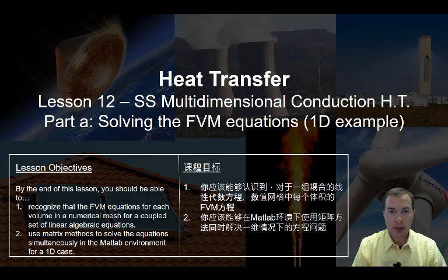By the end of this lesson, you should be able to recognize that the finite volume method equations for each volume in a numerical mesh form a coupled set of linear algebraic equations. You should also be able to use matrix methods to solve the equations simultaneously in the MATLAB environment for a one-dimensional case.